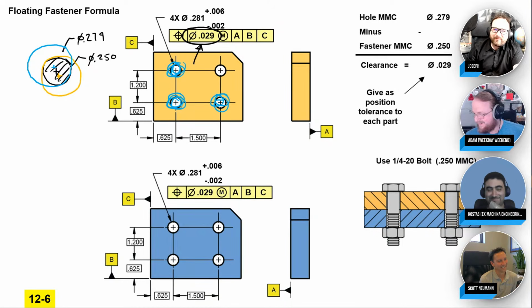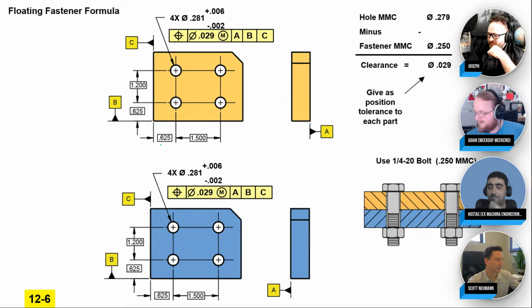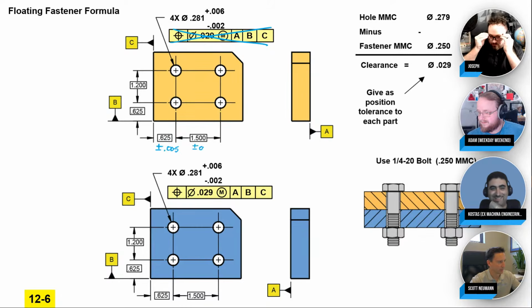If I remember my numbers right, this gives you 56% more tolerance than if you were using plus minus dimensions, right? That's right. Yeah, plus minus. Oh boy, that's a nightmare system. Because you have to put plus minus on instead of position tolerance. That's what we used to do in the 1800s and early 1900s. We used to put plus minus on the dimension, and on every single one. Yeah, you put a plus minus here, and you put a plus minus here, and then you put plus minus on this.